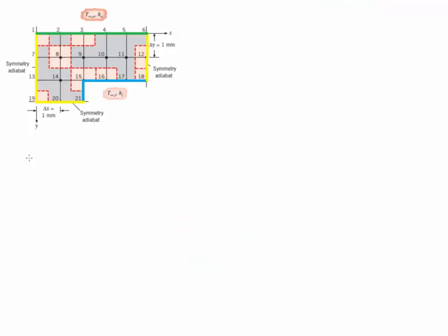The next step is to determine which nodes have the same boundary condition and determine the finite difference equation for each one of them. These nodes are located in a corner. They are exposed to insulation, conduction, and convection. The convection is to the hot gases. If we do an energy balance in each of the nodes, we get the following finite difference equation.